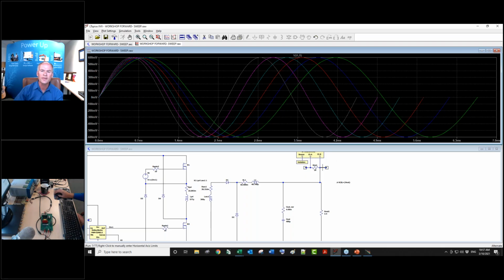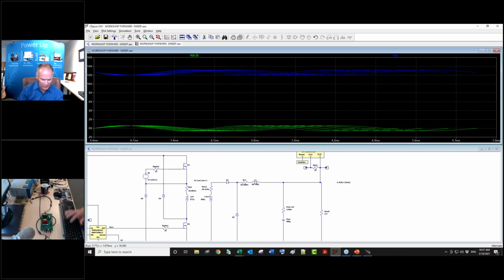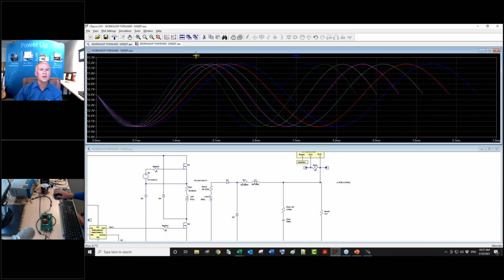All right, now let's look at the other signals. Let's just look at channel B, which is the output of the loop. Here's the output of the loop now. I'll get rid of the injected signal first. You get the point that it's not changing. Here's my output signal, and its amplitude is just about equal to the injected signal, because we've got a high gain loop. This injected signal of 0.6 volts has to distribute itself according to the loop gain between input of the loop and output of the loop. Right now, because the gain is high at these frequencies, it's all showing up at the output of the loop.